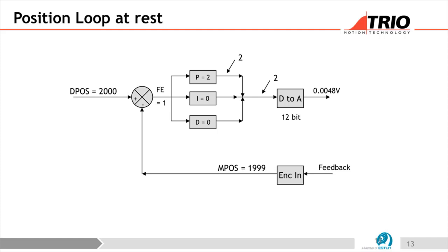And one of the issues with P gain is in systems where you actually want one axis to follow another, or you want to follow a track very accurately, is that you end up with following errors when you're moving. And the reason for that is, this is only a multiplier, and if I want to move that motor, say a quarter full speed, I need some voltage out of here. I need 2.5 volts. So again, if it's a 3000 RPM motor and I want to go at 750 RPM, I need to output 2.5 volts there to make it move, otherwise it ain't going to move.